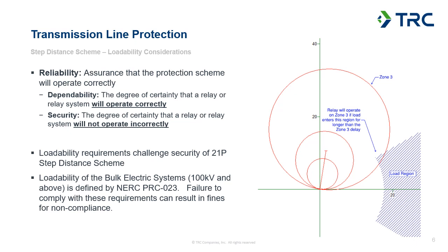So really, when we talk about loadability, we're coming back to the core concept of reliability, dependability, and security. And if we look at it from a security perspective, we're saying that we don't want the relay to operate for a condition that's not a fault. So when we talk about loadability, we're really talking about the security against loading conditions.